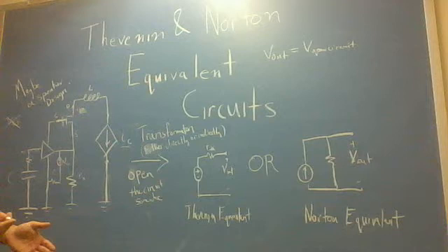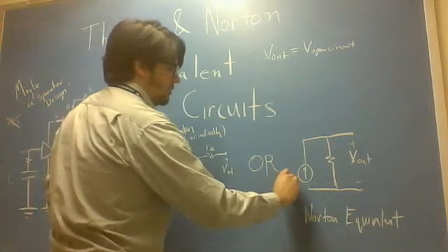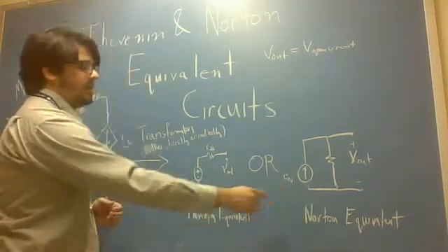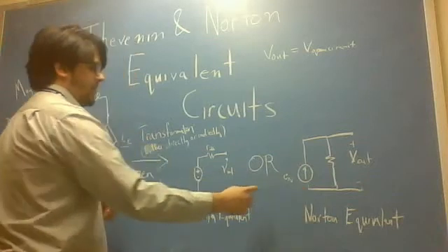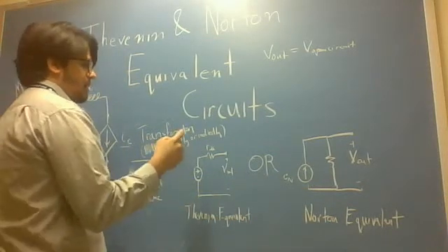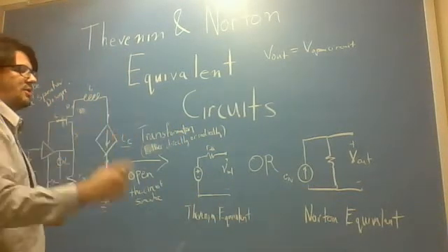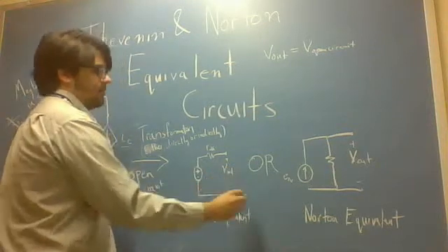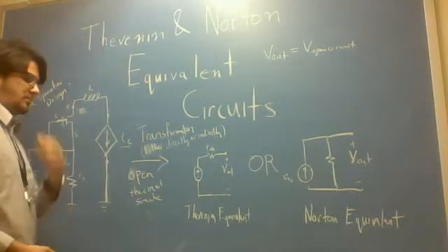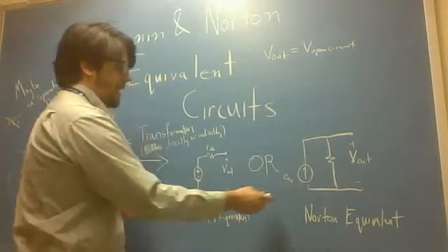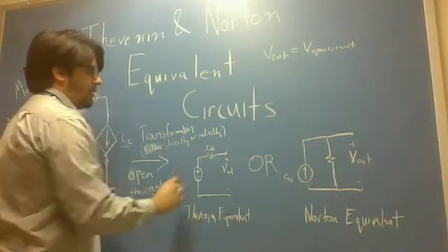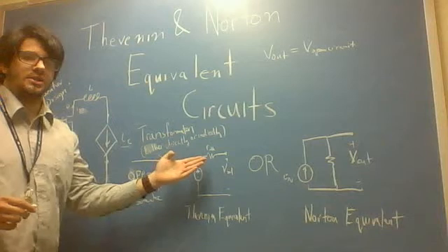And so what you would get then is that the current that you found would be the I Norton equivalent current, which would be in this circuit, and then if you found the V out, you would get the voltages of the V out here and here. Also, what you would do is divide V out by I N to get the Thevenin equivalent resistance.